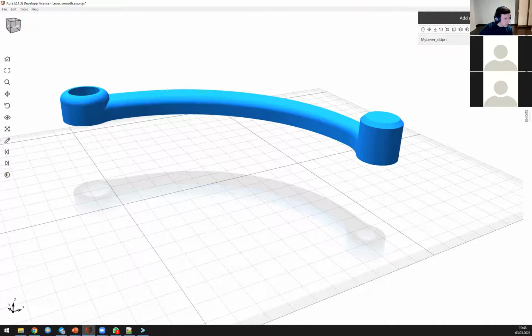Okay, so is there a way to set and control loops forming in a mask, such as the one shown with 3 holes for larger masks? For example, if I wanted overlapping loops going from each small hole to the large hole, or would I have an approach such as creating each loop for itself as a separate mask and following that, layer by layer? Yes, the only approach here is to create several masks and to put these masks one above another in that direction.